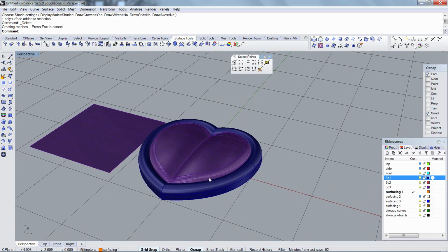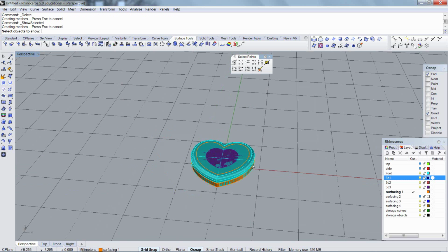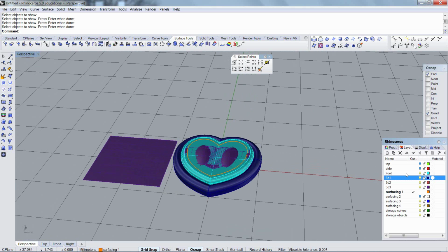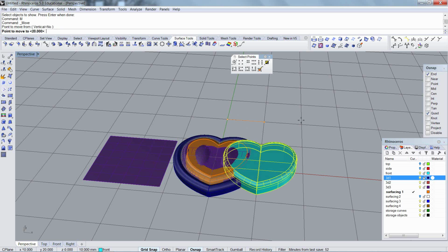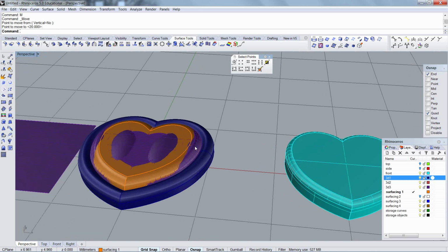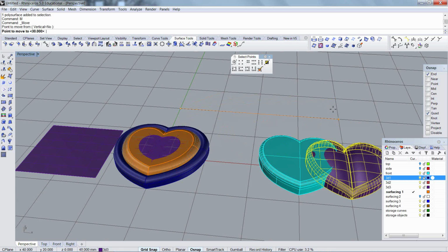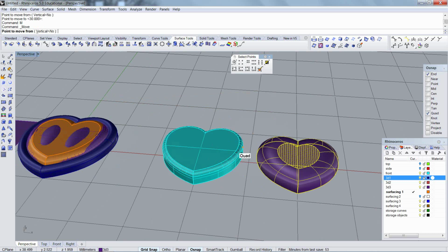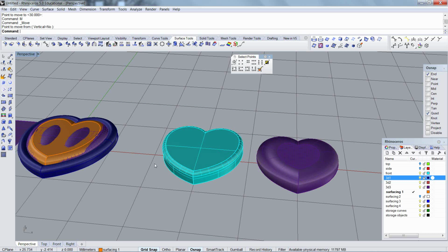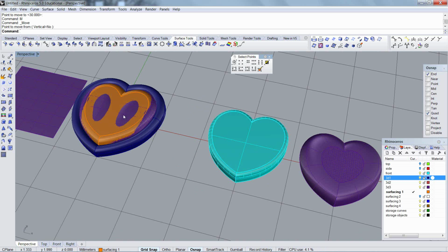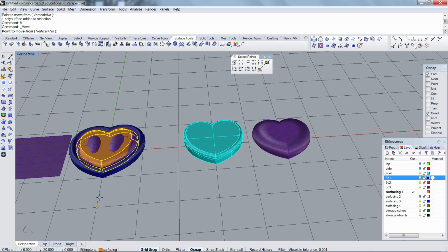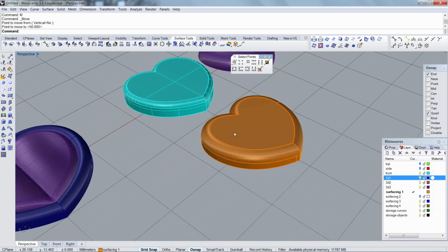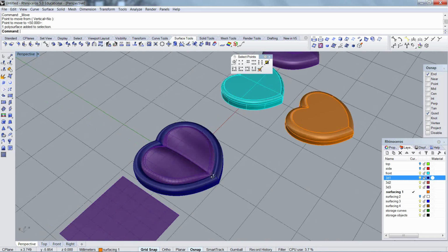So in summary, I used, let's unhide some things, a simple extrusion with a cap, a revolve, sorry, simple extrusion, not with a cap, simple extrusion with a fillet, a revolve command, a rail revolve with a patch, a pipe with an extrusion and a patch, and a flow along surface with control point editing.